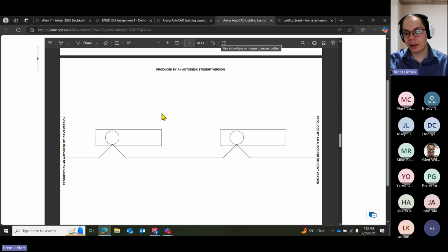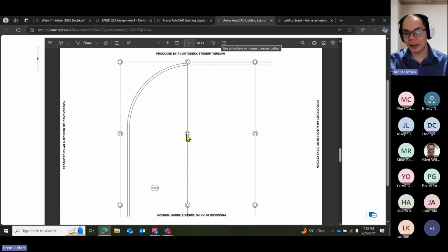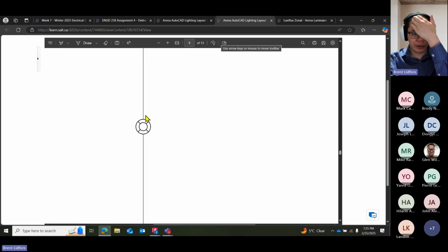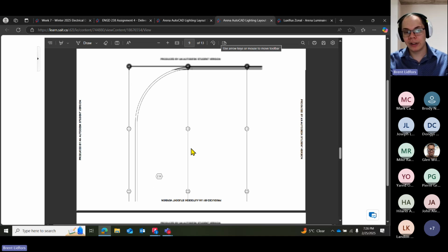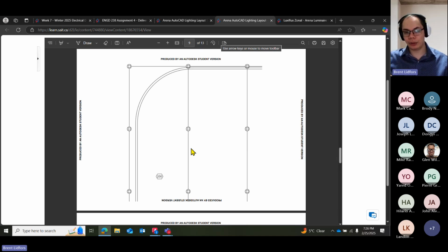This details file also kind of shows that. Same with the medallion lights. When you place it on your grid, it's going to look like it passes through these medallions. When you actually go to make the conduit, again, the conduit itself doesn't run through the symbol. There shouldn't be any conduit within the symbol for the luminaire itself. Again, just for organization, showing that it's a connection to the luminaire, but it's not part of the symbol. So if someone goes and prints this out in black and white and your line goes through the symbol, now it's a bit ambiguous about what exactly that symbol is supposed to be.